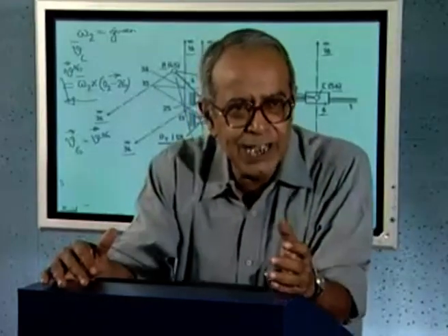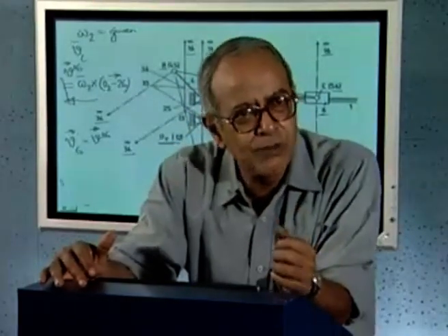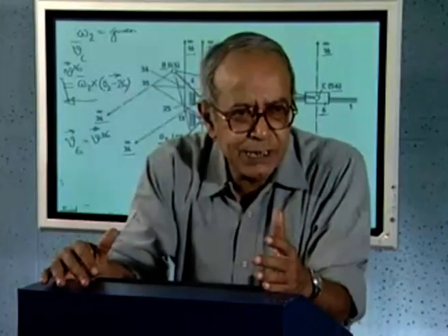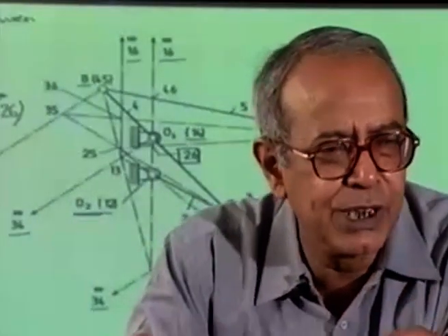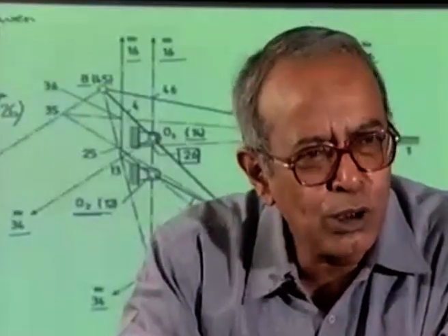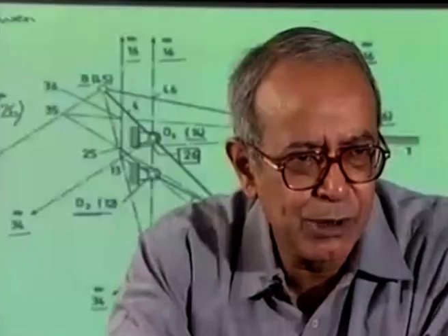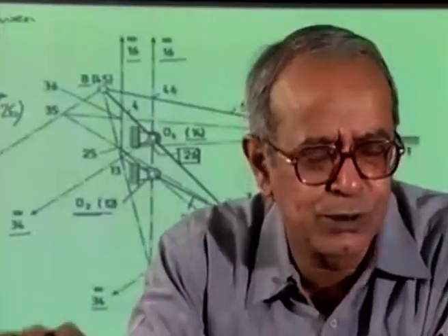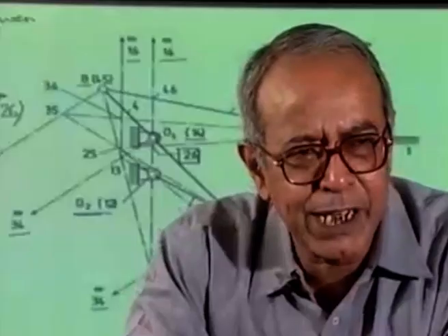So in today's lecture, we have seen how to determine all the relative instantaneous centers of planar linkages by considering the different kinds of kinematic pairs and by successively applying the Aronhold-Kennedy theorem of 3 centers. This method is definitely going to give you a result so long as you have not more than 6 links in a mechanism, which is sufficient for the purpose of this course. So for a 6-link mechanism, there are 15 relative instantaneous centers, and all of which can be determined.